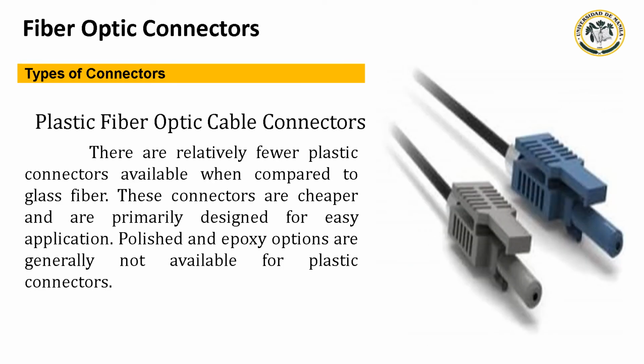Next is the plastic fiber optic connectors. There are relatively fewer plastic connectors available when compared to glass fibers. These connectors are cheaper and are primarily designed for easy application. Polish and epoxy options are generally not available for plastic connectors.